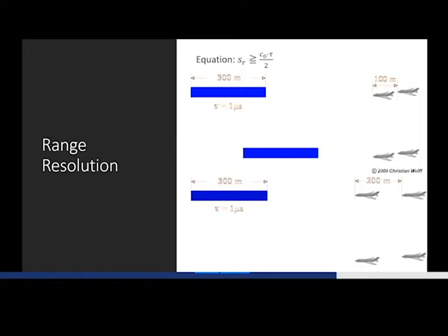For example, a well-designed radar system with all other factors at maximum efficiency should be able to distinguish targets separated by, as shown in the equation below, 1/2 the pulse width time. And so when you look at the figure 2, it shows that since the theoretical range cell of the system